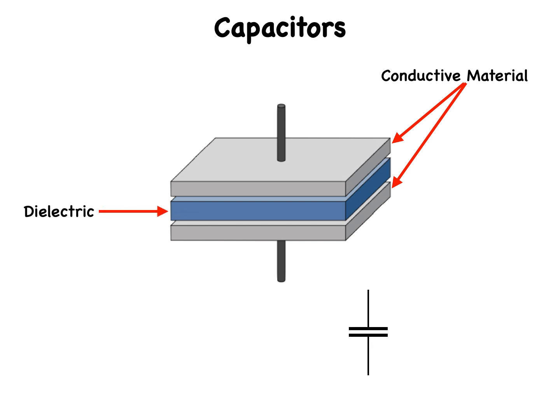Notice that the symbol for a polarized or electrolytic capacitor is the same as the one for the non-polarized, but a plus sign has been added to one side. This sign indicates that the positive terminal of the component goes to the positive of the external circuitry. Occasionally, a negative symbol will also appear on the opposite side.